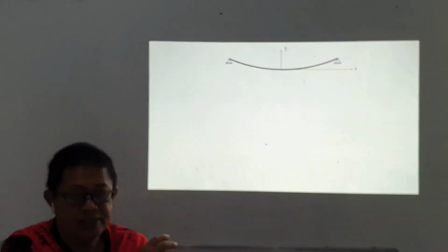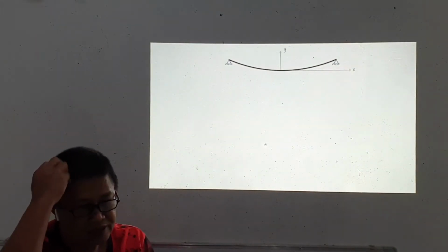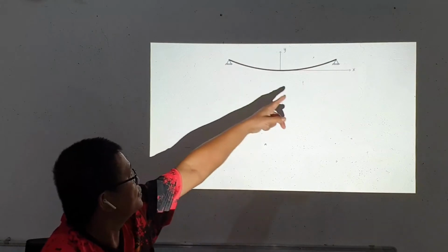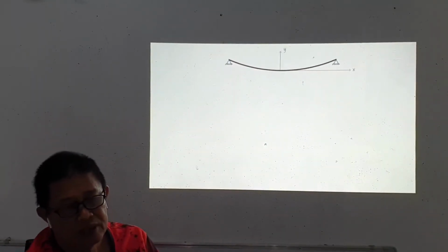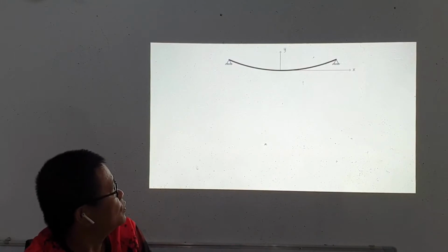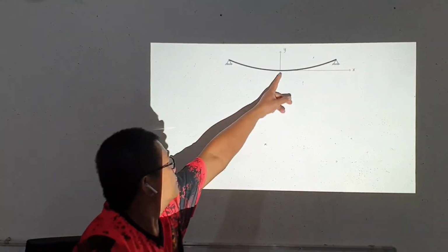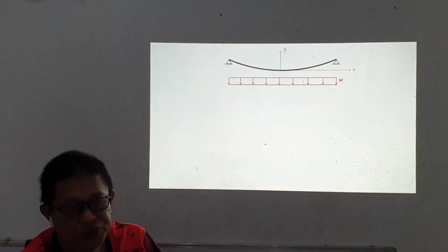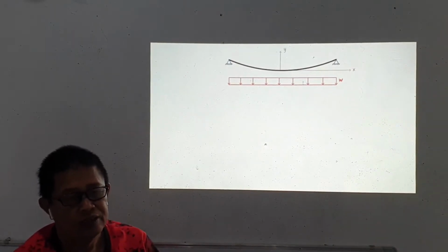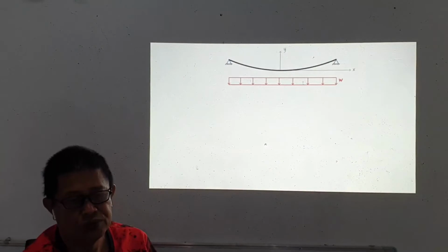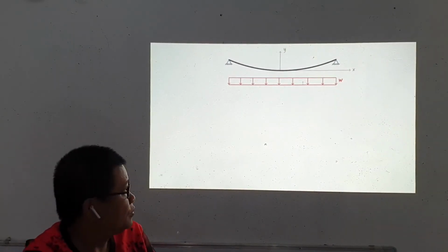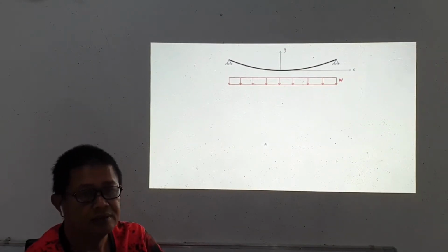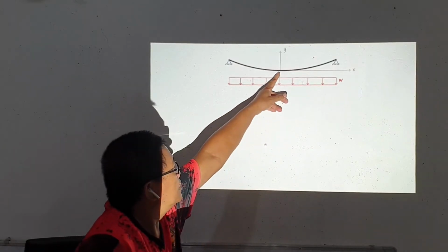So if we analyze first the parabolic cable, we represent the supports as pin connected, and the cable will have its lowest point at the 0, 0 of the XY axis. The load is distributed uniformly, and to derive the equations for the behavior of the curve, let us consider a certain infinitesimal, small length from the origin.